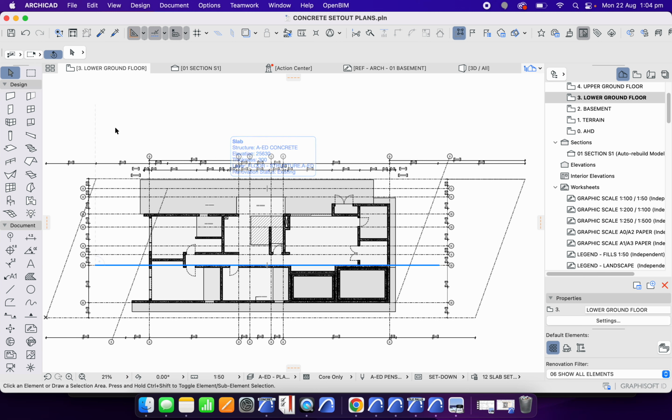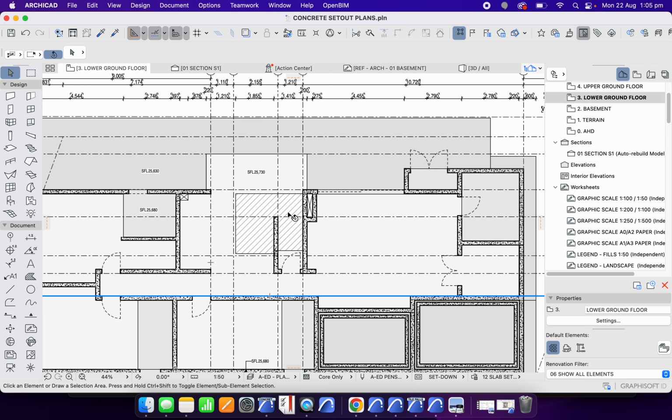becomes inconsistent. And of course, once those grids are drawn and once the surveyor puts those grids on site, I can't move those grids. Now the walls might change, but I can't change the grids. So it's really important that they stay the same and that they're accurate with their representation.